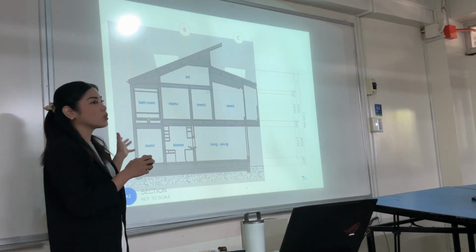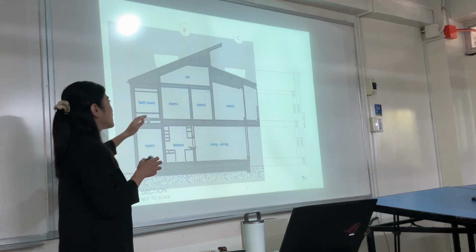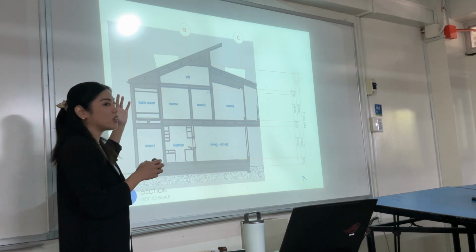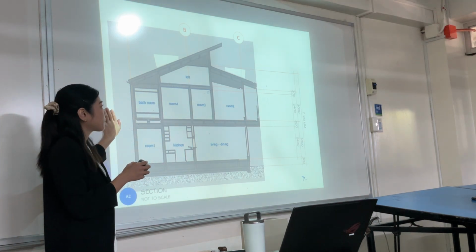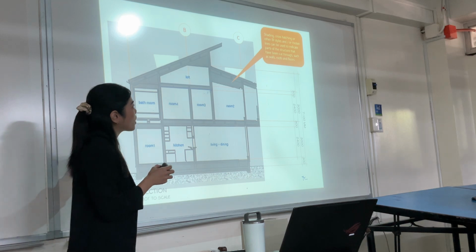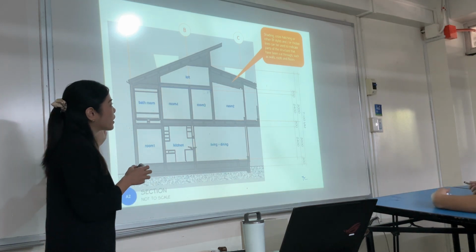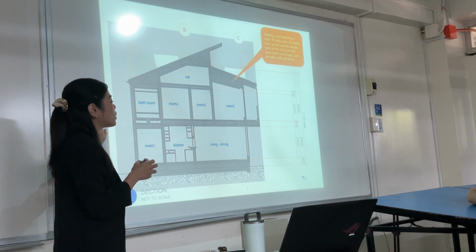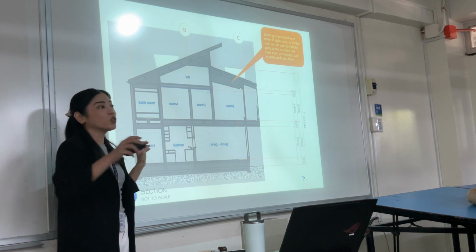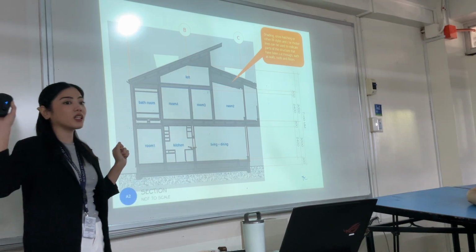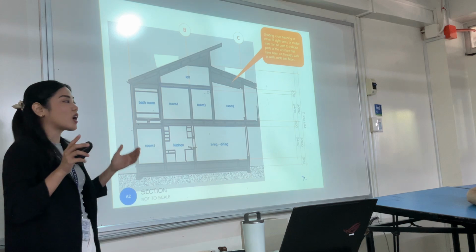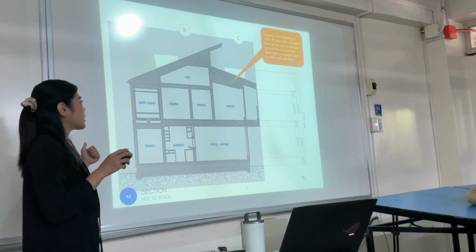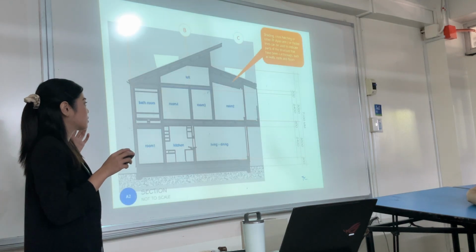And then, most very common mistake is, hindi sila nag-label ng rooms. Make sure na i-label nyo ang rooms kung saan yung makat nyo. Okay? So shading, cross-hatching, or other fill styles and or thicker lines can be used to indicate parts of the structure that have been cut through, such as walls, roofs, and floors. And even to the point na ang door frames nyo. Kung nakat nyo yan, anything that has been cut, dapat i-hatch nyo, use very thick lines to indicate na naka-cut mo yan siya.